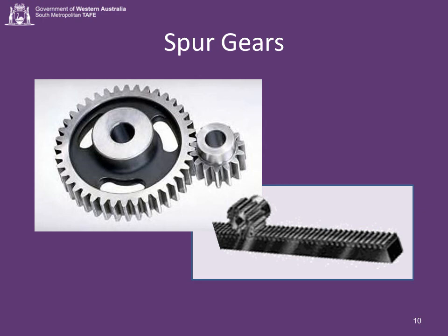The involute system of spur gearing is based on a rack having straight or flat sides. All gears made to run correctly with this rack will run with each other. The shafts are in the same plane and parallel. The teeth are cut straight and parallel to the axis of the shaft. No more than 2 sets of teeth are in mesh at any one time, so the load is transferred from one tooth to the next tooth rapidly.